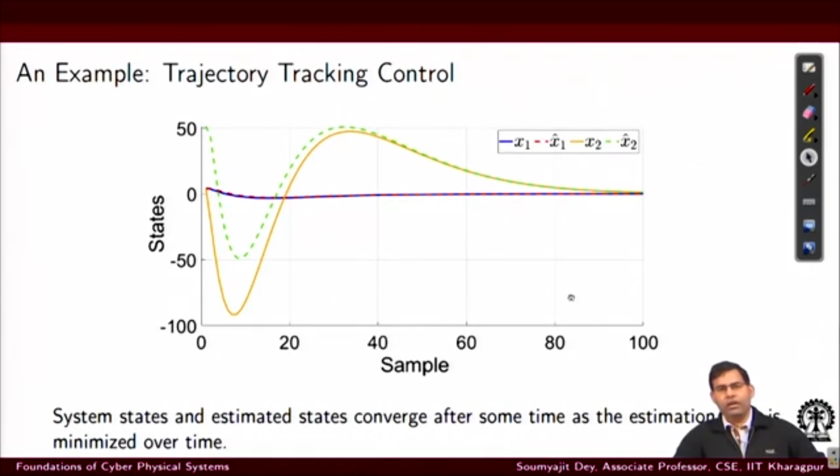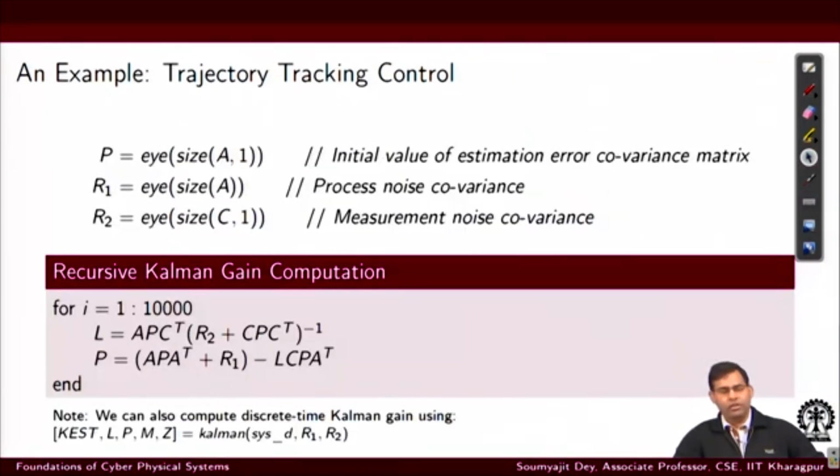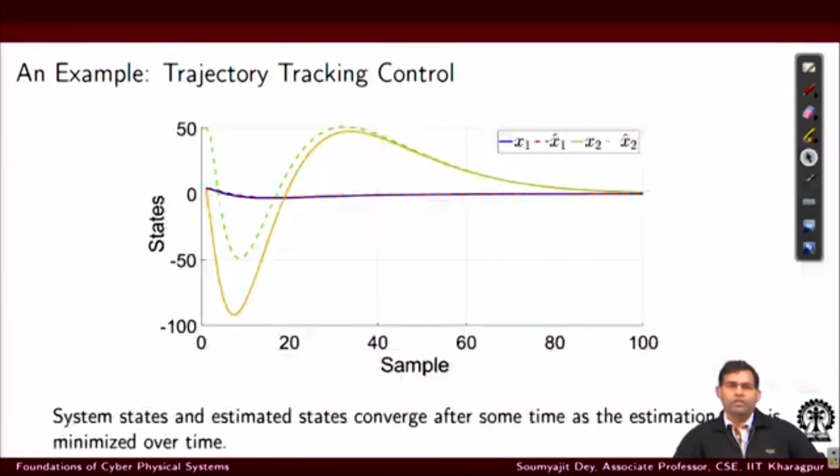With this we end our derivation of how a Kalman filter based estimator can be designed. So, as you can see, it is basically a minimization in a least square setting, and the way we derive the filter gain is using a standard minimization technique of optimization, and with this we will end our lecture.